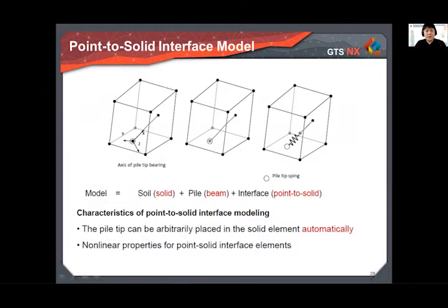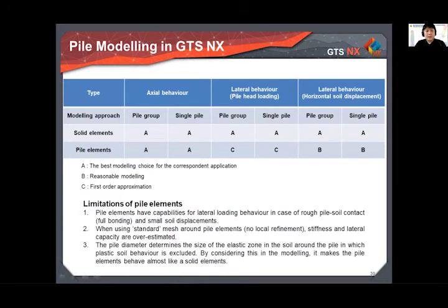And this is about the pile tip element. At the bottom of the pile, you can consider the tip bearing capacity as well. The pile tip can be arbitrarily placed in the solid element automatically. And this slide shows a comparison between using the solid element and the line beam element for piles.